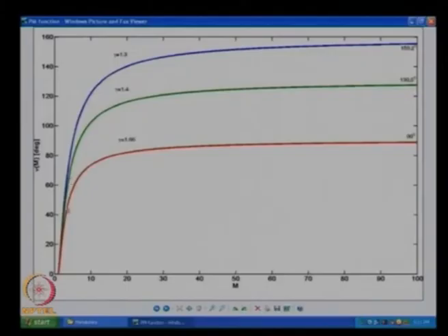But anyways, if I pick any particular curve, let us say this green curve, we see that there is a lot of change initially up to around Mach 5 or something. All of them have a lot of change, and after that they slowly steady out. This is the speciality of hypersonic flows. When Mach numbers are above 6 or 7, most of the variables start tending to become constant. We will deal with that more if you are doing a course on hypersonics, but we will just leave it with supersonic flows. Ideally I would zoom in only from 1 to 5.